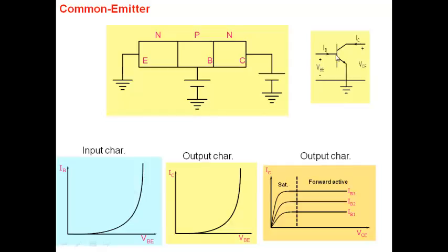So similarly, when I'm looking at a transistor, in all the circuits that we'll encounter, we don't keep the base emitter voltage fixed, assuming that the collector current would then get fixed at a certain value, because it's so sensitive. What is common is that I'll keep the base current constant. I apply a constant base current and then look at what happens to the collector current. Okay, so that's a much more useful configuration. That's why you're seeing the collector current versus collector emitter voltage plotted for various values of base current here. IB1, IB2, IB3.